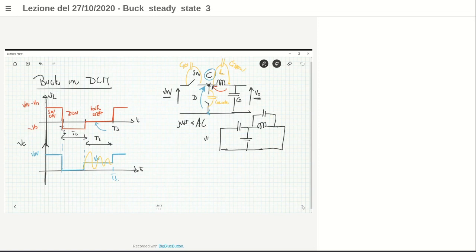Okay, in which I put V in and V not to be 0, because I'm just looking at the AC circuits that holds when you have this range. Okay? So in that situation, you have an inductor which is in parallel with some parasitic capacitance. So this is a resonator, and the resonance is 1 over square root of L C parasitic.